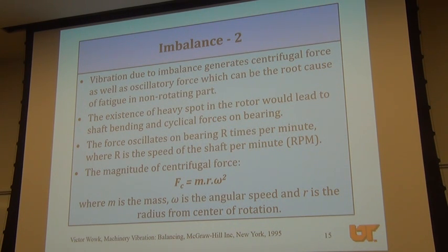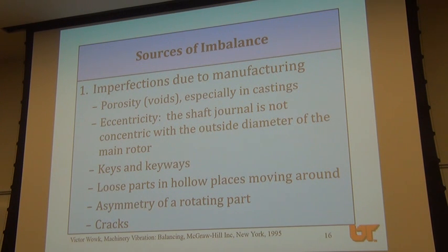Higher the force, greater the vibration, displacement, or the force acting on the bearings. Some sources of imbalance: most of the time the imbalance is probably caused by manufacturing defects. Sometimes they are caused by humans, because I go to repair something, and I don't do the repair properly, so then I can induce certain amount of imbalance or fault in the system.